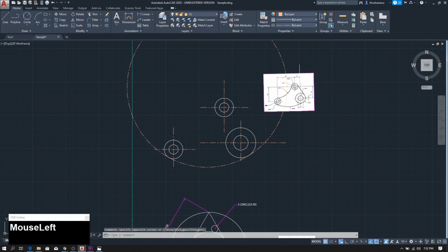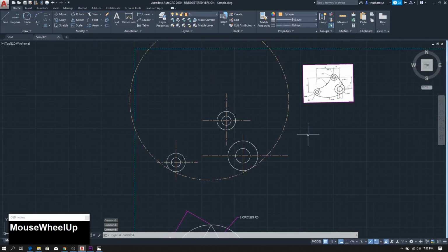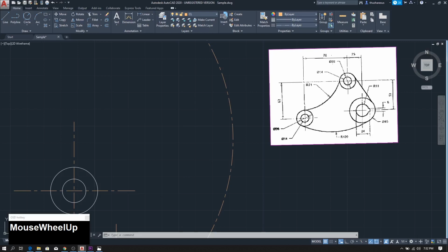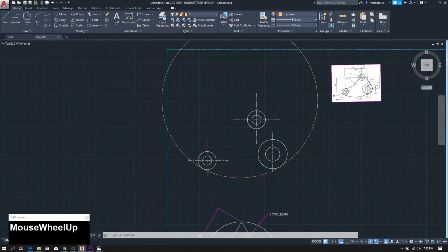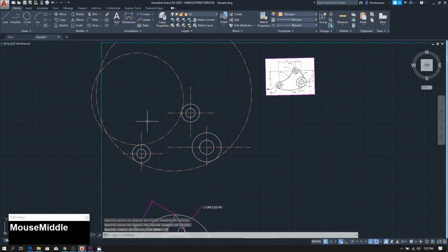Please, I will move this picture to here. Okay, now you can see what this is. Then I want to create this curve. That curve is touching this circle, this circle and this circle. To draw that, the radius is 71 millimeters. Go to tan radius again, and select this and this. Move the mouse here and put 71. Okay, those are the two curves in our component.